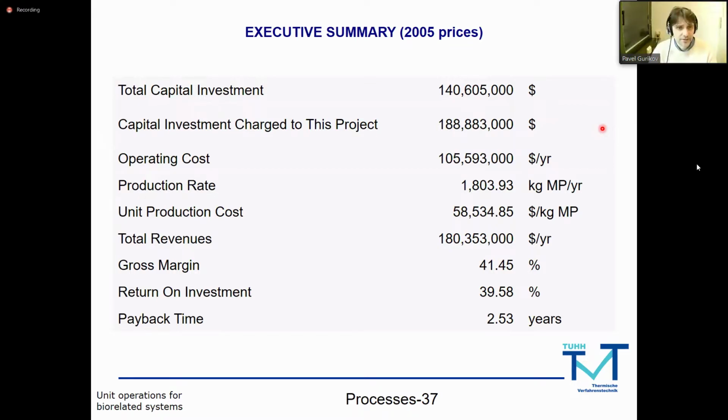Gonna show you the next slide. What is production rate? It is how many batches we can process per year, 160, and we multiply 160 by 11.5. That's how we arrive at the production rate per year. So this is the amount of main product, in kilograms, you get after the freeze dryer. It's not that much. It's less than 2 metric tons. That's what you get basically in hand in your stock after the year.